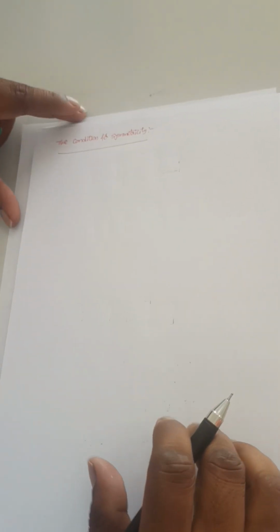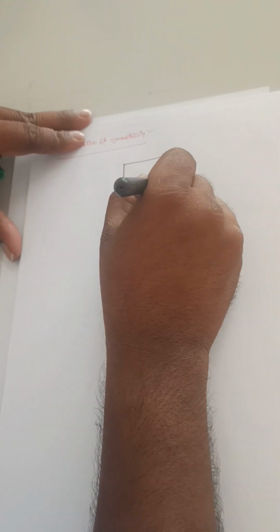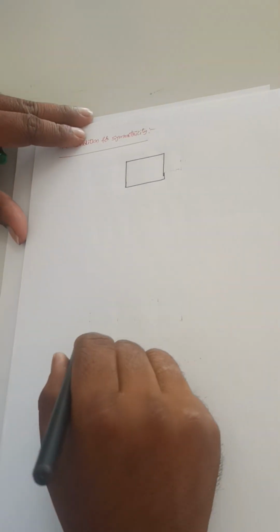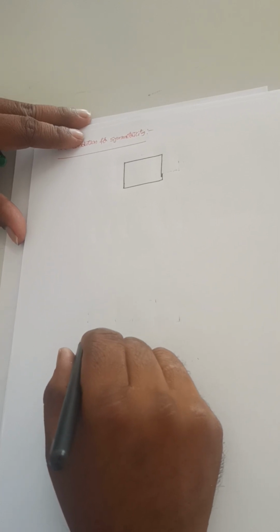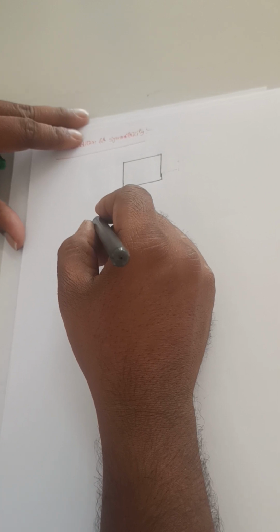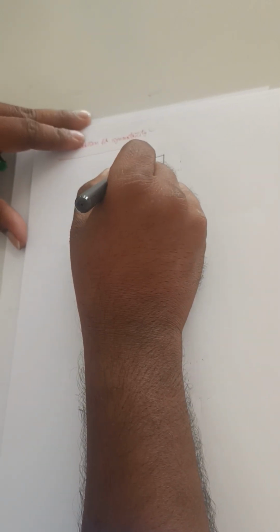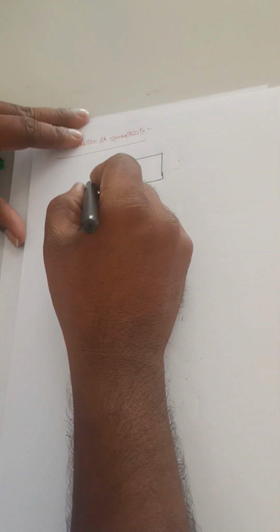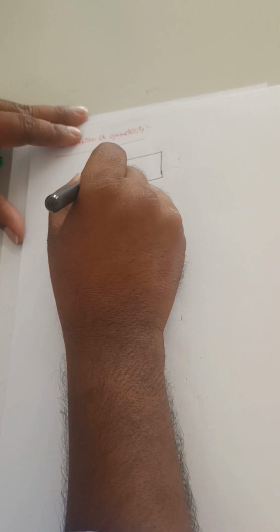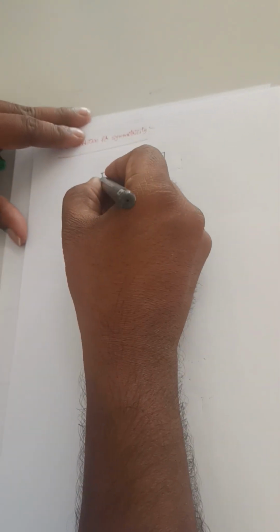As per the definition of this symmetricity, the network is said to be symmetrical if the ratio of excitation and response at the same port should be equal to the ratio of excitation to the response at the other port, provided one of the ports should be open circuited. So let me derive this and let me explain clearly here.